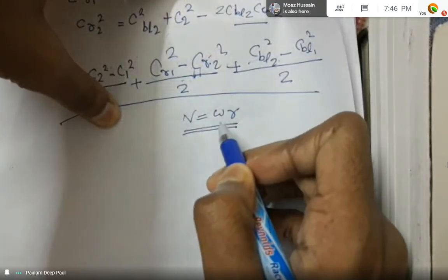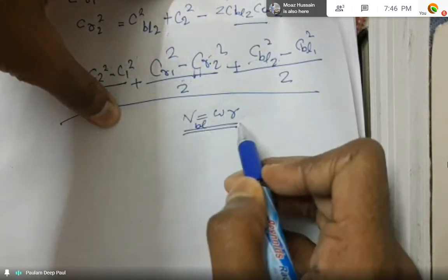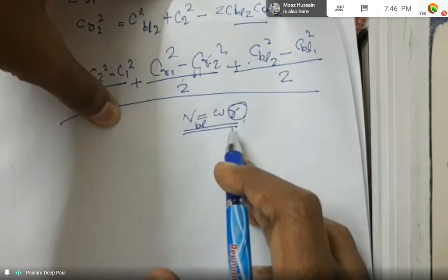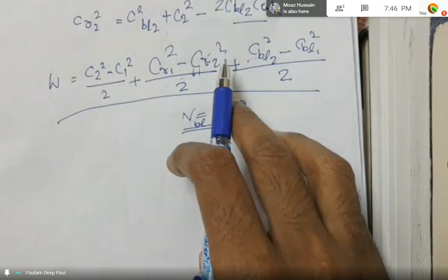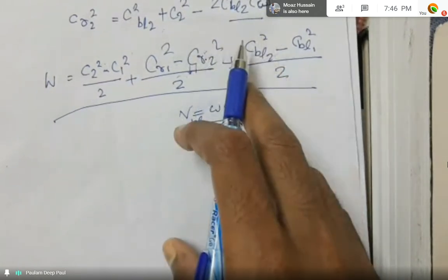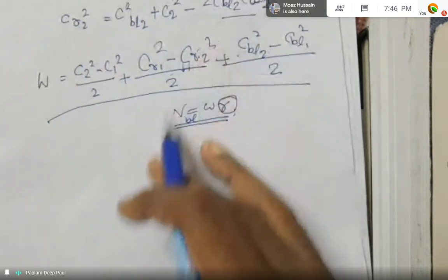So we know that the blade velocity will increase or decrease depending upon the radius. The inlet radius would be lesser than the outlet radius. So there is the centrifugal action as the working fluid enters at a lower diameter and comes out at a higher diameter. So the third term shows the pressure rise due to the centrifugal action.